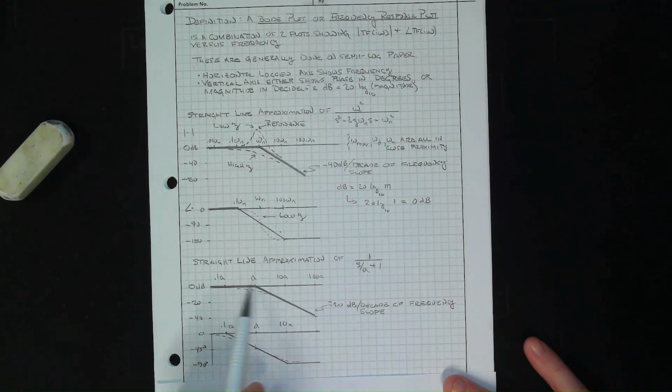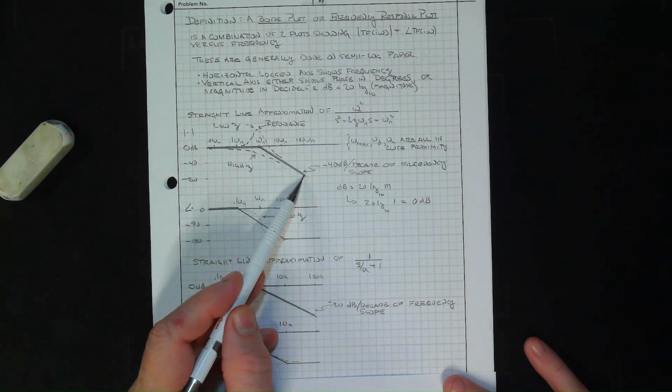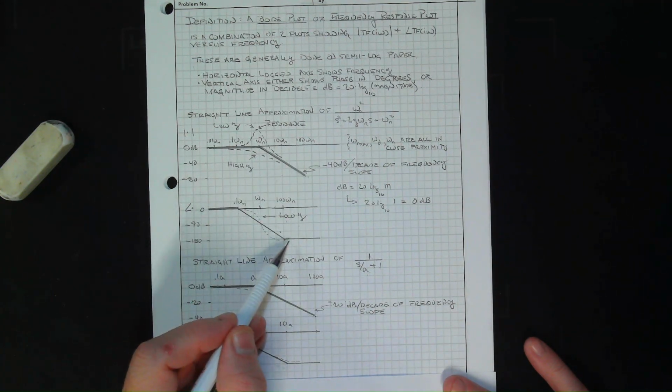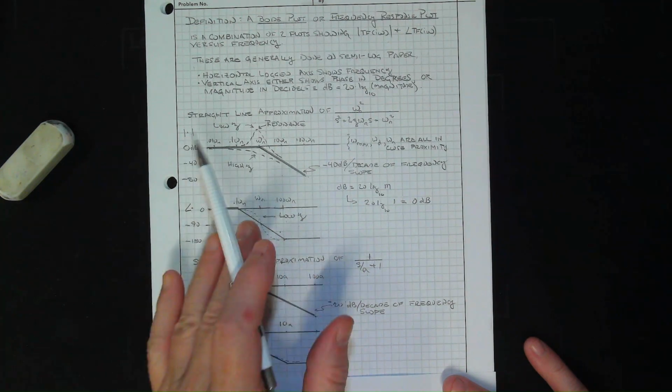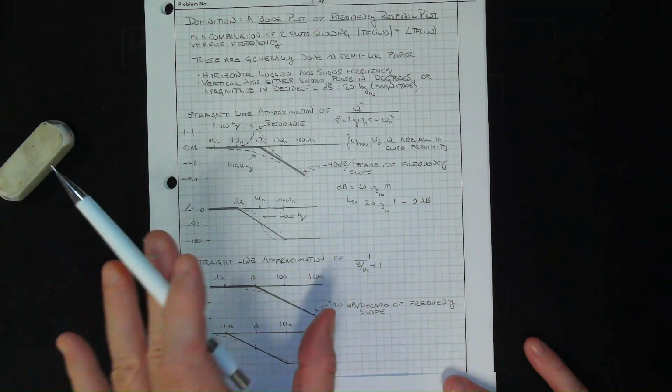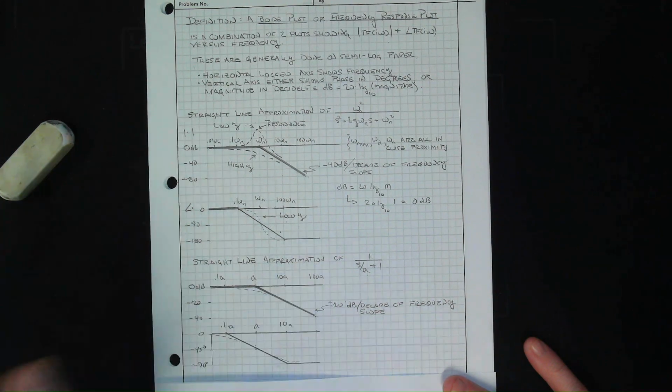All right, so it can track a sinusoid. As you start getting to higher frequency, it can't keep up, so the amplitude is going down. And it's losing phase in terms of keeping track with this. If you have a second order system, it's worse. It falls off faster, and it loses more phase. Okay, mechanical systems are naturally low-pass systems.